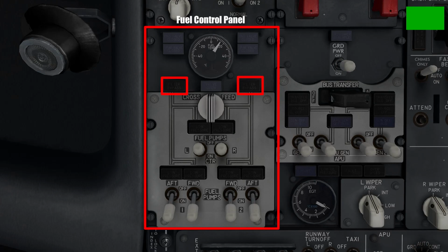Normally, fuel from the tanks passes through an extensive filtration process before being injected into the engine for combustion and thrust. However, in the event that one of these filters experiences a fault or a failure, instead of cutting off fuel supply to the engine altogether, fuel will directly be fed into the engine without the filtration process being applied, and the light on the appropriate side will be illuminated.